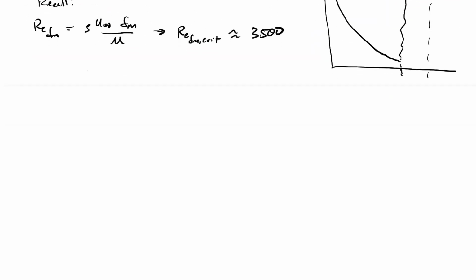All right. One of the things we usually care about is the pressure drop in a duct like this, right? Unlike in external flow, where, let's say, it's the wind blowing over your plate, or you're driving your car and you have flow going over the car, you don't really care too much about the pressure drop, at least for the convection correlations or whatever you're doing. Unlike that situation, in internal flow it's almost always the case that somebody is paying to move fluid through that system. Or you have a pump, you have a fan, there's gravity head or whatever it is that's driving that flow through that duct or pipe.